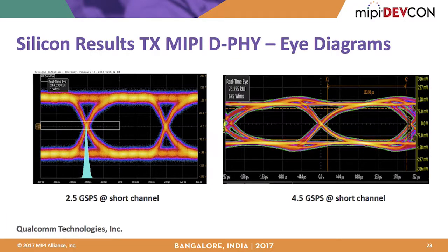We actually use the same TX design, so it doesn't add extra capacitance. Of course, some tricks are required, but the message here is that the same driver can be used for both C-PHY and D-PHY. If you have two different drivers, they will add more capacitance and hurt each other, but this is a combo, so the same driver and the same receiver are used.